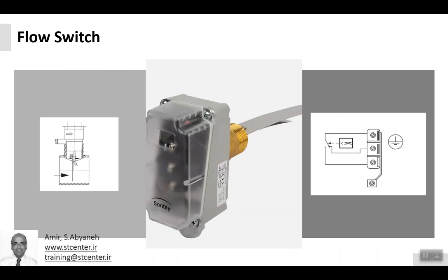We talk about the flow switch. For the flow switch, you should take care of the installation instructions from the manufacturers. Also, it provides us only one contact. You remember we use the digital input. So we should take care of the wiring.